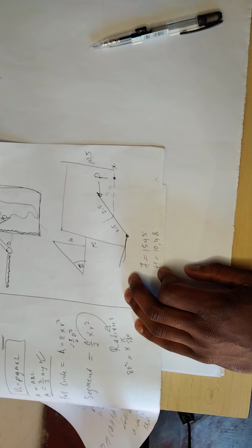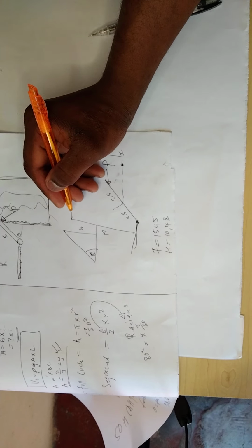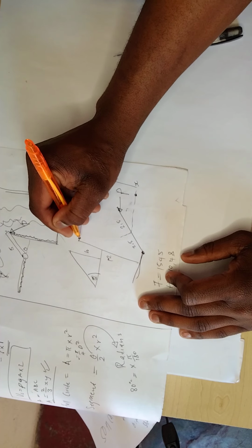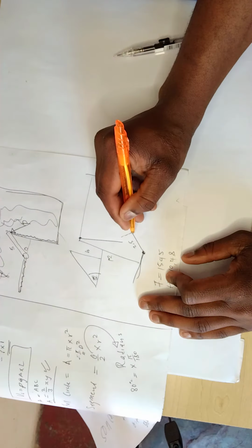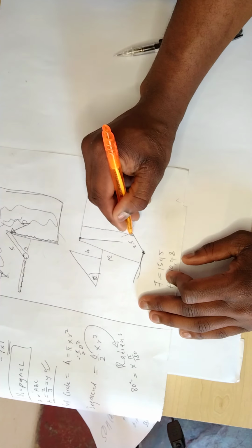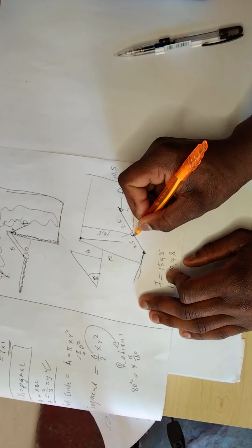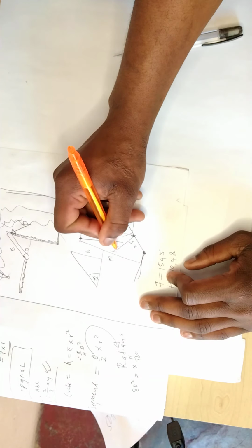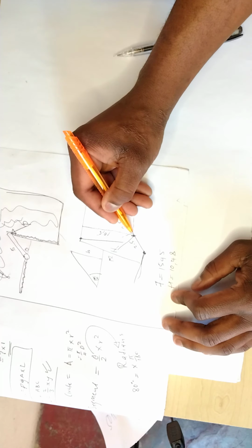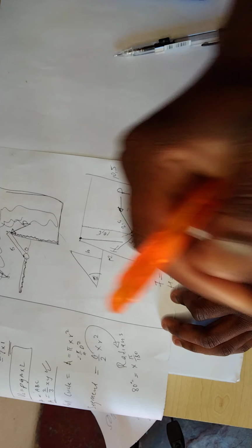I want you to note something. You have to measure from the top going down here. You can start here, you measure, you measure, then you're going to get your 10.5. Where your 10.5 acts, that's where your force acts, not on the centroid. I always tell people that the force always acts underneath the centroid.